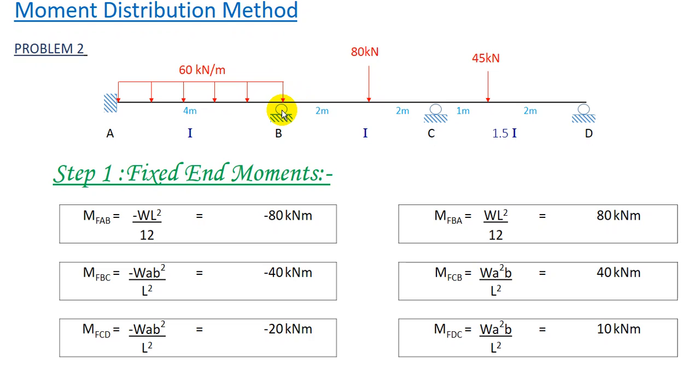The first step of the problem is fixed end moments. Okay, if you are not well versed with fixed end moments, you can find the tables in which the formulas for various kinds of loading of fixed end moments will be given. Let me assume that you already know fixed end moment, and we'll proceed further.